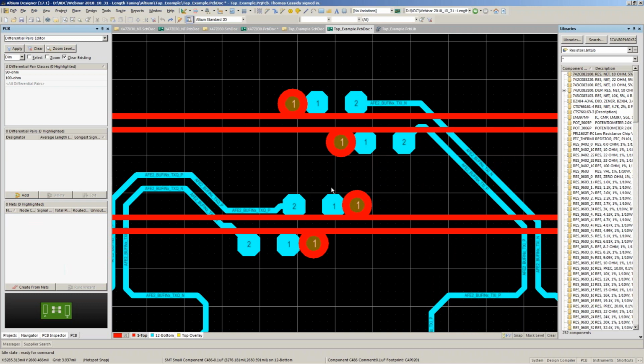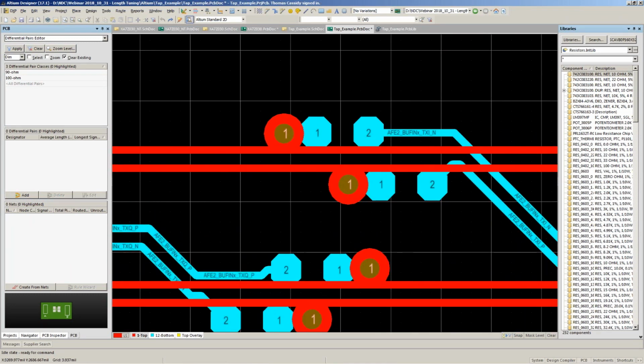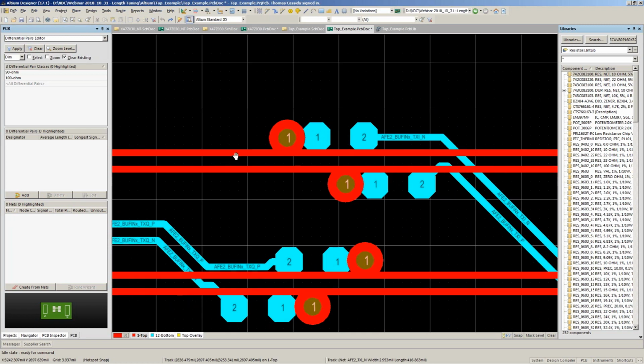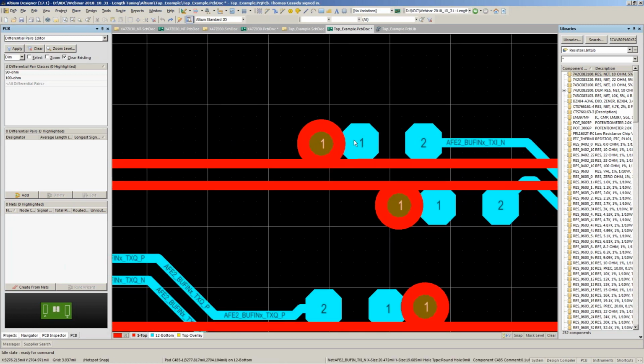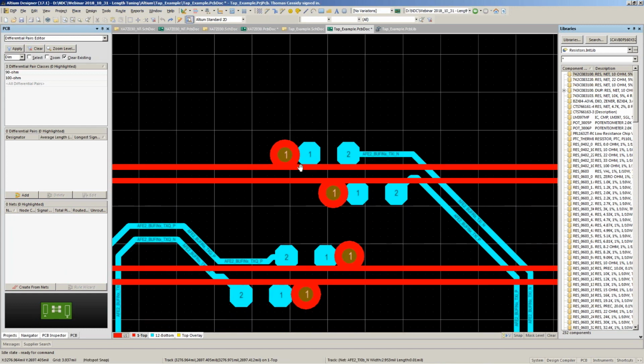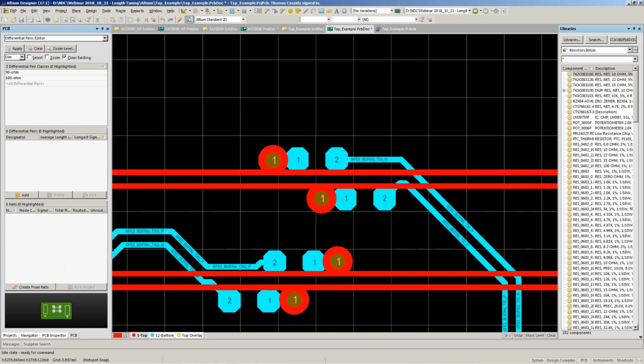I just want to take a quick aside here. I had several comments in the questions about why I picked such a weird shape for my taps on this. These were gigahertz level signals, so having a very clean impedance routing was pretty important, and we had to make some trade-offs because of that. Several people said, why don't you just go through the via? I could have done that, but then we would have introduced wider trace spaces and different impedances. This maintains my nice straight pass-through of copper and then taps off to the edge. So it's about as minimal a Heisenberg uncertainty as you can get: try not to affect your signal by looking at it. That's why this came out kind of weird.